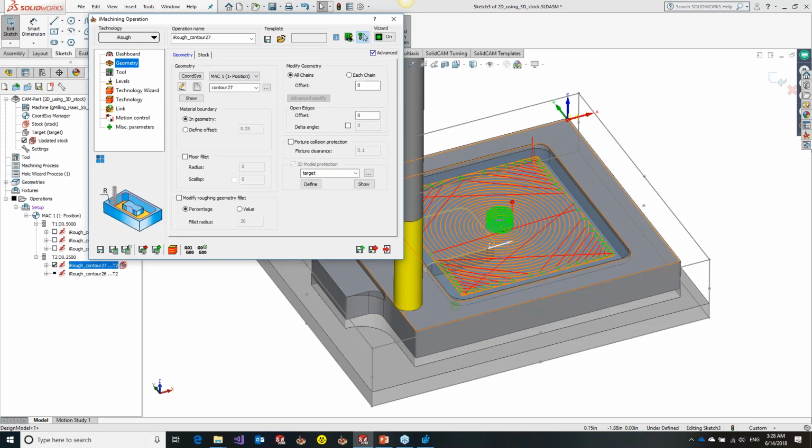Because with iMachining 2D, we take care of all the technology. We never plunge on stock. We do all the smart repositioning. The toolpath is optimized because we use engagement angle. The wizard is there to figure out all the feeds and speeds and depth of cuts for the tool you're picking, for the material you're picking. And now you have multi-tool, so you can define multiple tools in one operation, how you want to completely rough and finish that geometry. And then the geometry selection is going to be as simple as just picking on faces.